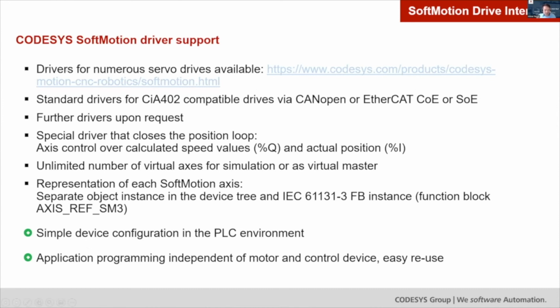The difference to the specific drivers is that this is our interpretation of the standard, and we cannot test it with all available drives on the market, and therefore there's a certain risk that it maybe does not fully work from scratch, but there are some parameters you can set in the standard drivers to adapt it to almost any model that claims to support CiA 402 or EtherCAT SoE. Further drives and also this testing of the drives we can do on request.